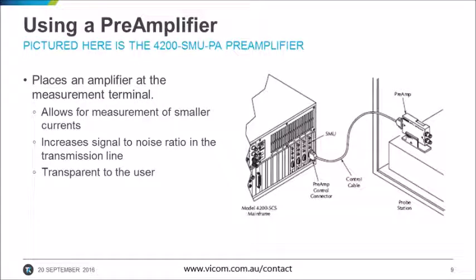For very low current measurements, which includes very high resistance measurements, as in the previous example, the signal-to-noise ratio can grow quite small over a rather short cable. A small amount of noise on the cabling tends to produce a pretty ugly signal. The easiest way to eliminate this noise is to move the measurement system closer to the device under test. However, as many of you with probe stations or similar setups can attest to, there is usually not enough room for an average-size instrument right next to the device under test. Nor is there an effective way to mount it there.